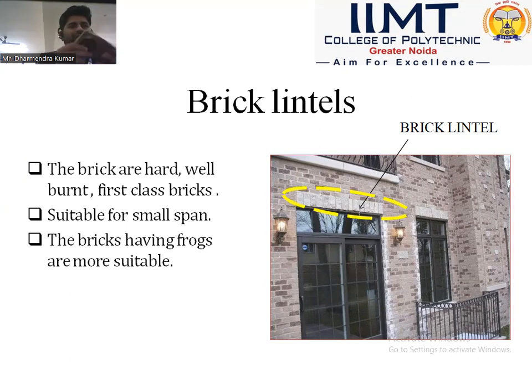The bricks required are first class, with a compressive strength of 10.5 Newton per mm square and water absorption capacity should be 20% of the dry weight, and this is suitable for small spans.